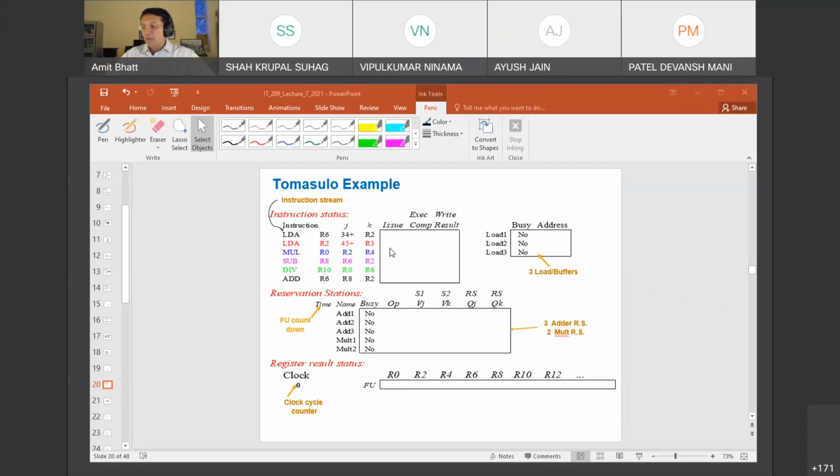Now, you should also remember that when people design a general purpose processor, it is not for a specific case. So you may design a particular thing with, say, 2 load and 3 ALU and maybe 1 or 2 MAC. And if you have a whole lot of MAC instructions, some of the MAC instructions may have to use your simple ALU.